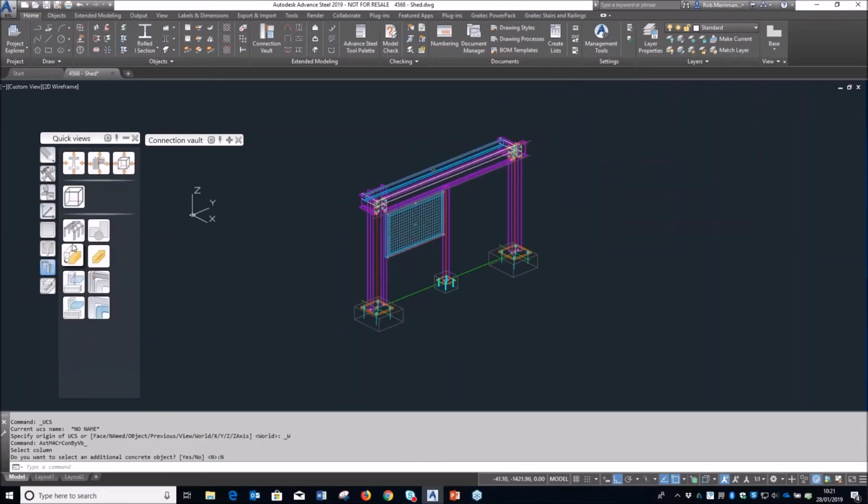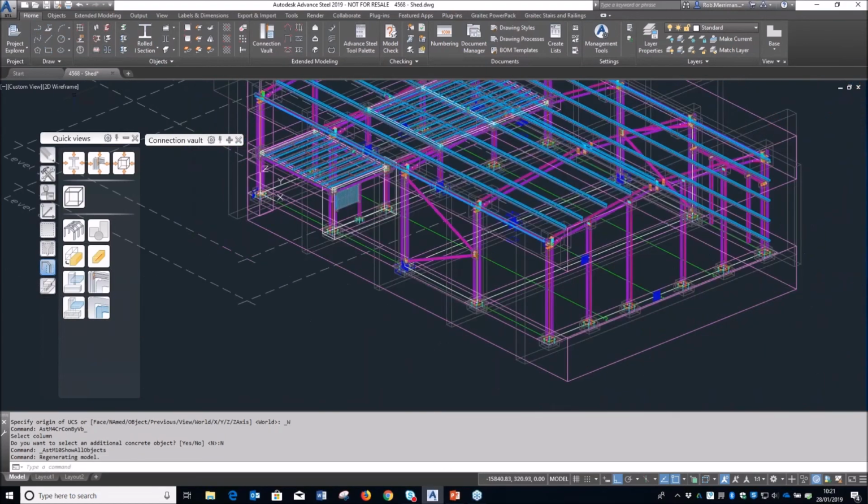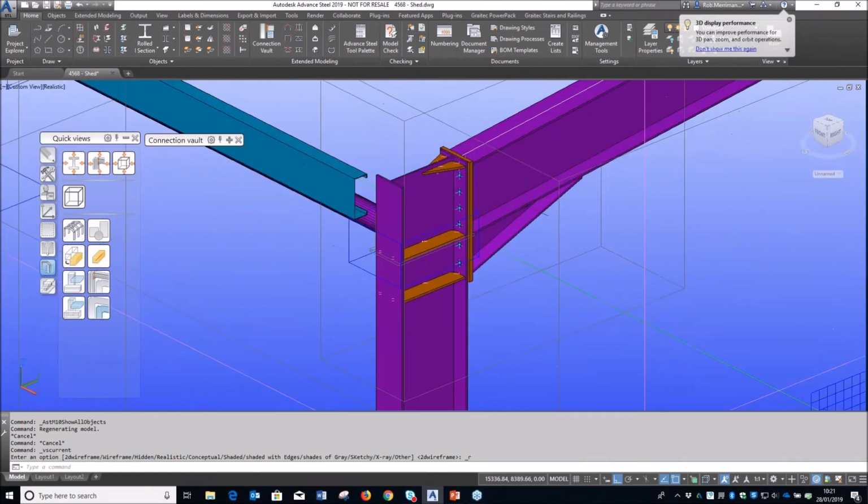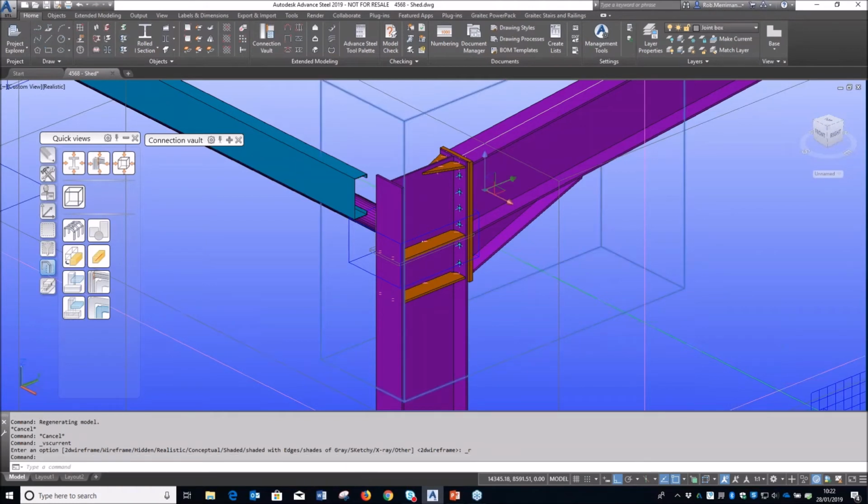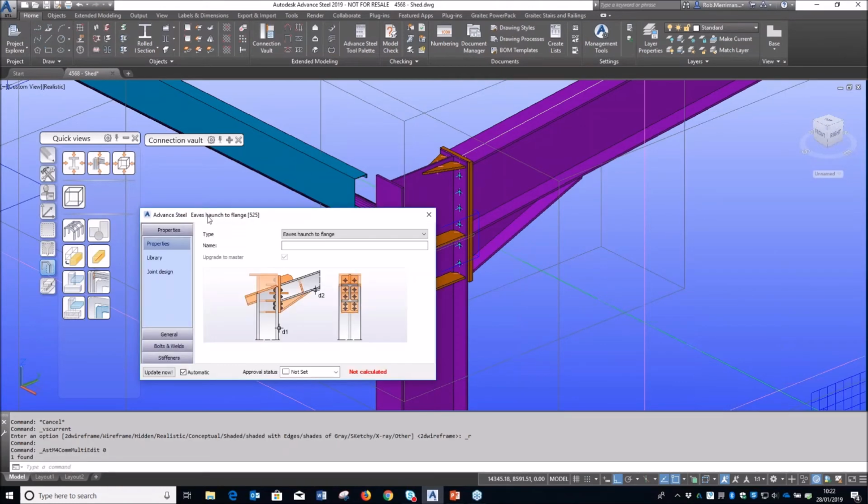And then the last little bit we'll look at for data is bolts. So let's just tidy this up a little bit. So we'll come in here. So a lot of projects these days, you have to follow CE marking procedures. And you also know that bolts also need to be specified according to CE marking, and they need to be specified correctly as ISO bolts. So for example, a grade 8.8 partially threaded bolt needs to be EN ISO 4014. So we as Graitec, like I said, the bolt data has been created and added into the system.